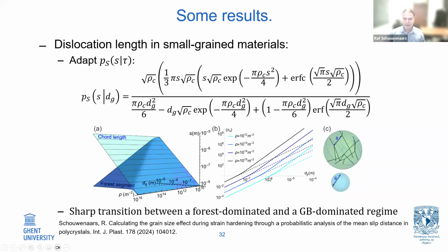In this grain, it's easier. The number of segments per grain at 10 to the minus 6 crosses here the zero axis. This is logarithmic, so this means one segment. Below that, for a density of 10 to the 12th, it makes no sense to talk about these statistical dislocation mechanisms because dislocations will just run from one side to the other. As the dislocation density increases, then of course we will see an increase in the number of segments. And it is of course known that even in nanometer-sized grains, we can still form smaller subgrains.